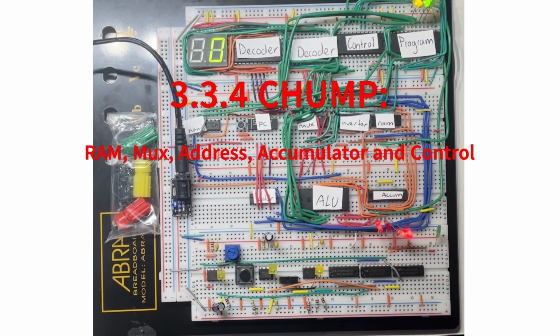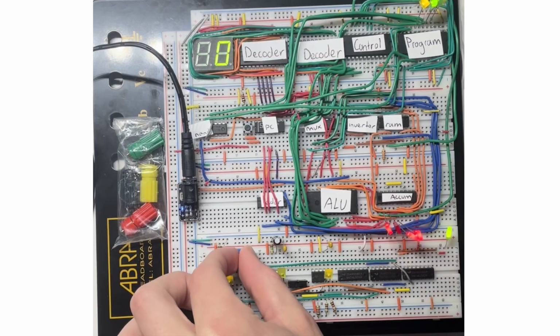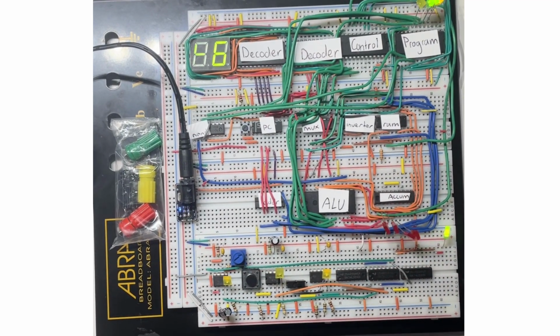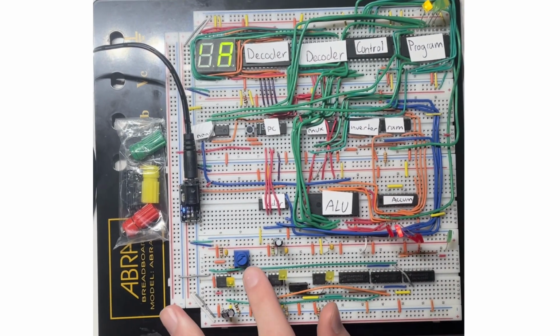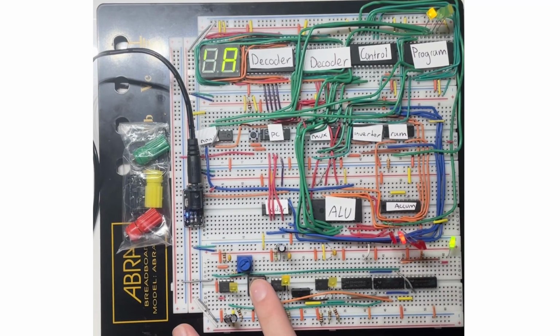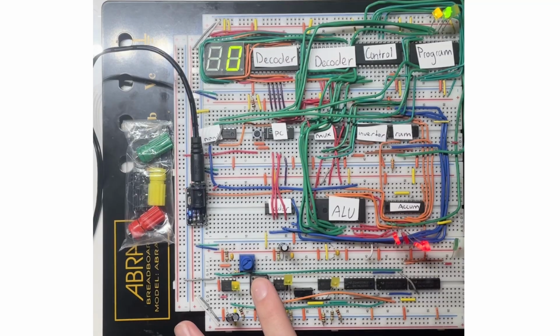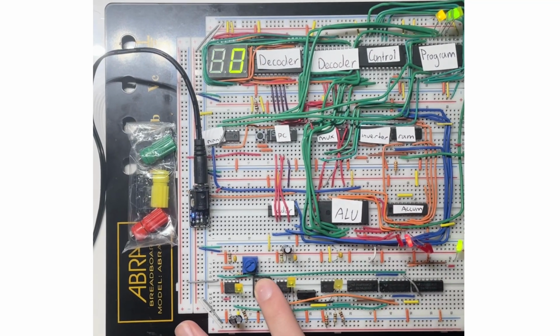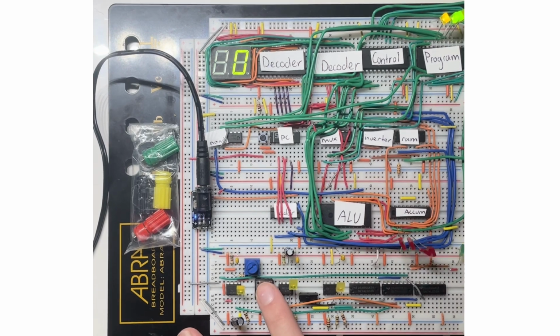The foundation of the memory system is the 74LS189 RAM, a 16x4 static memory chip that provides temporary storage for variables, intermediate results, and program data. The RAM accepts a 4-bit address from the address register and uses the control word to determine whether it should read or write. A low pulse on write enable captures the data present on the bus, while a high state replaces the stored value onto the bus during read cycles.